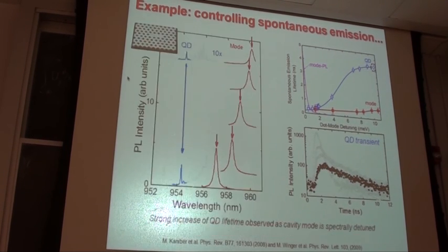Can you say a word about the picture at the top left, exactly what we're supposed to interpret that as? This one here? No, the graph there. That is the cavity. It's a membrane of semiconductor which you drill holes in to make a photonic band gap. And this region here confines a single cavity mode because of the distributed Bragg reflector in all directions. So it's a very small cavity. To give you a length scale, that is of the order of 500 or 600 nanometers.